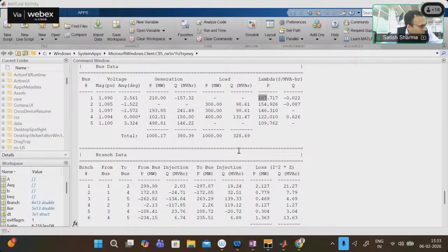Sir, another question. The second order cone relaxation for OPF is there. Why is that being used? There are different relaxation techniques: SOCP, second order conic programming, SDP is also there, and some McCormick relaxations are also there. If I try to solve the very fundamental OPF problem I have given to you, I will not look for relaxation. It can be solved, and you can see a very simple piece of code was able to solve it.